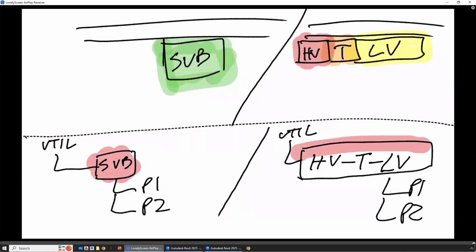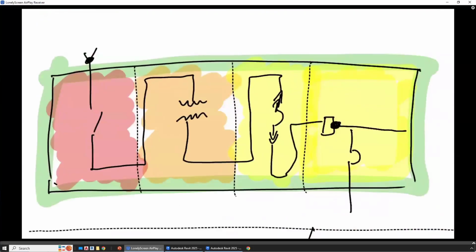Going back up to the single line diagram, if you do it as those separate pieces, you'll then have each of these items and you'll have calculations again at the top and then at each of these locations here. And so then you can account for that for the calculations for fault and voltage drop. Again, what you do depends on what you're trying to get out of the calculations. If you need to take that into account, or if you don't want to try and model all of that. There's no necessarily right answer. Just understand your options, and then you as the engineer need to figure out what information you have, what you need to figure out.